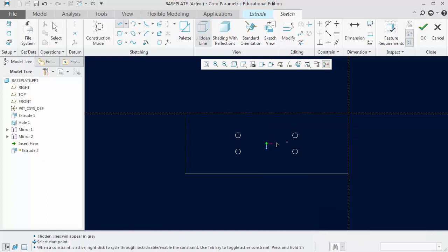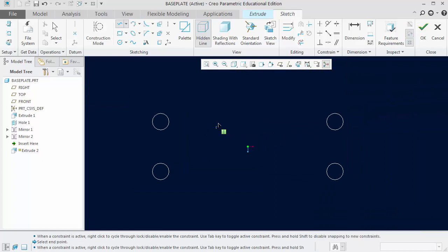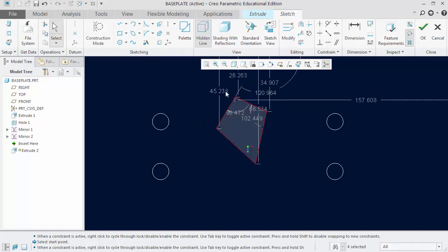I'm just going to be sketching some lines here, and I'm sketching them off of horizontal and off of vertical on purpose. If I hit escape twice, you'll notice the enclosed sketch loop is gray, which is what it should be. What's new in this case is that if you keep hitting escape, it doesn't try to exit Sketcher anymore. I'm not going to change the dimensioning scheme or dimension values at this point. You know how to do that.